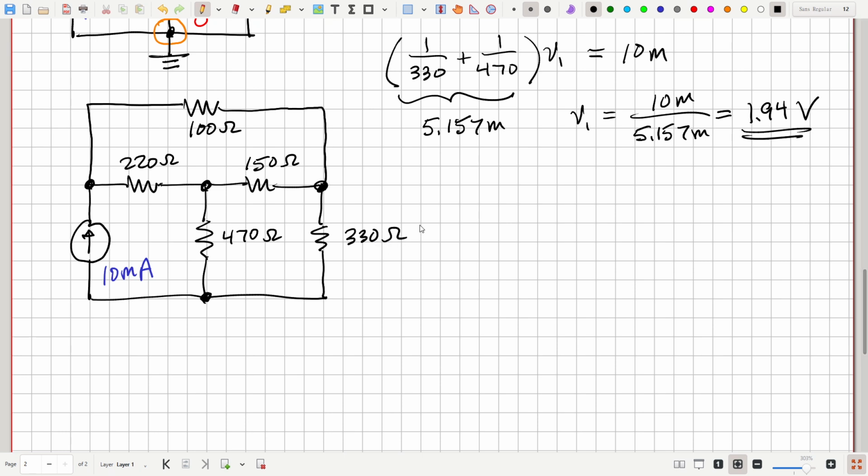Let's solve this circuit using the node voltage method. All right, first step, identify all essential nodes where 3 or more devices are connected. And those usually end up being the places where we put the dots, because when you connect 2 devices, you don't need to put a dot because it's obvious that they're connected. But okay, so here we go. There are 4 of them, 4 essential nodes.